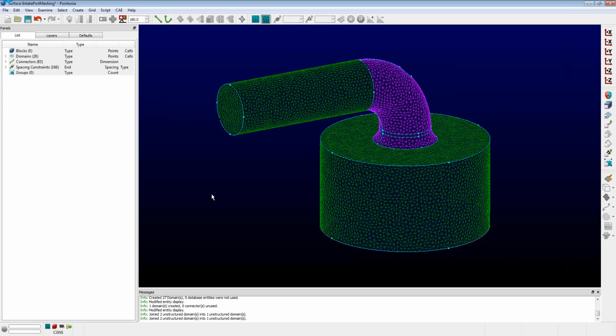What it refers to is the method of initialization. So a green domain goes through a 3D non-parametric meshing technique. It's initialized through a series of decimation, refinement, and projection steps, whereas a purple domain goes through a 2D parametric meshing algorithm. Okay. In this case, you see the purple domains are one domain per quilt, and that quilt has information about the underlying geometry and its UV parameterization. So it goes through this 2D parametric meshing algorithm. Whereas when we start joining domains over multiple quilts, those quilts know nothing about one another, and so it resorts to a 3D non-parametric meshing technique.